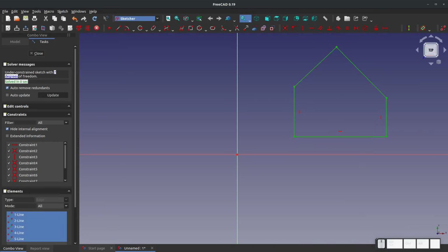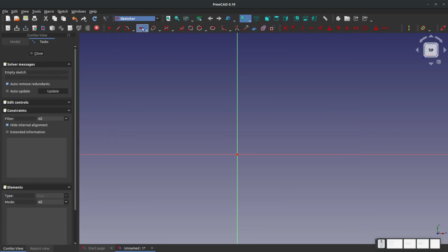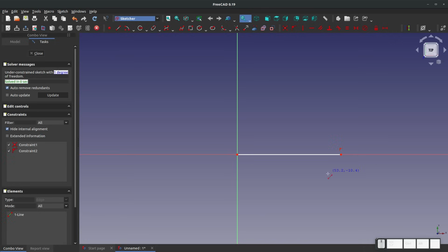Maybe I'll delete my house shape and go line by line. I'll grab one line, or my line tool. I'll highlight my origin yellow, as I've done before. And I will go to draw a horizontal line. You'll notice on the lower right of my cursor, you have that little horizontal line. That looks a lot like the horizontal line in this little toolbar up here. That's telling me that if I click in that position, it will automatically add a horizontal for me, which is what I want. Now, if I check to see how I can move this line, indeed, it only will move horizontally.